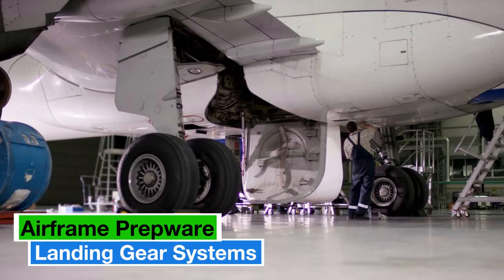What is the minimum amount of time to wait for tires to cool before checking tire pressure? 3 hours. If a shock strut bottoms after it has been properly serviced, the strut should be removed, disassembled, and inspected.